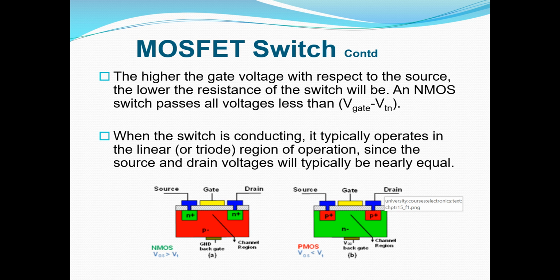That is nothing else but Ohm's law. If the transistor is conducting, more current passes, that is, electrons are passing from source to drain, and then the resistance goes down. So if the gate voltage is more, then the resistance will be lower.